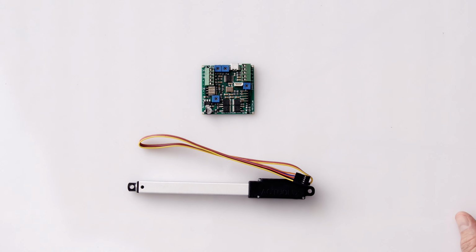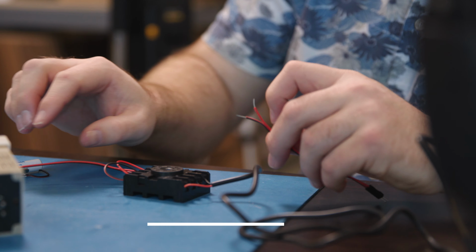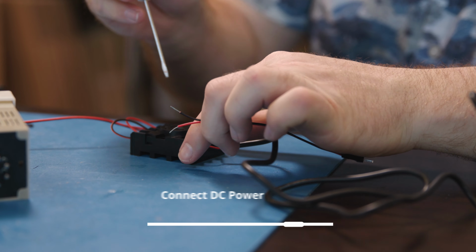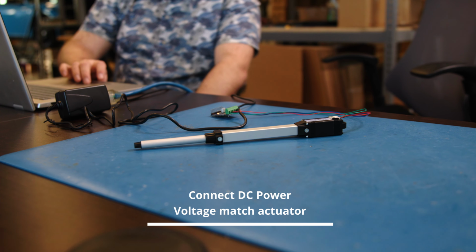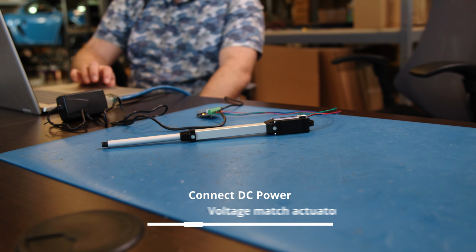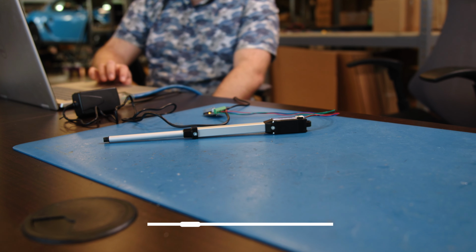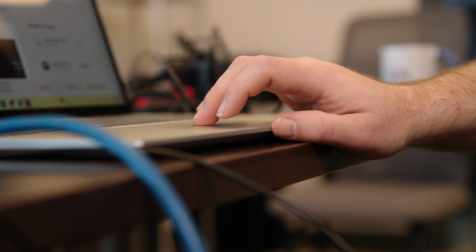Now for feedback type actuators, you can use our LAC control board. Connect DC power to the LAC's plus and minus terminals. The voltage you select should match the rated voltage of the actuator, 6 volt or 12 volt. Connect the actuator to the 5-pin terminal. Ensure the yellow wire is aligned with the pin marked yellow. Now you can connect the USB cable between the LAC and your computer.